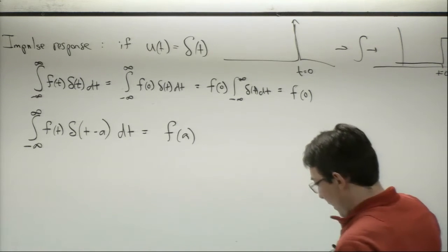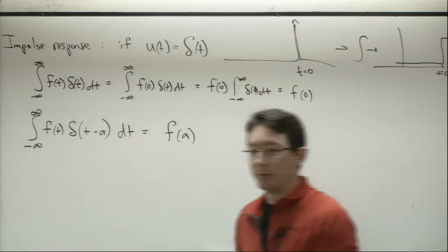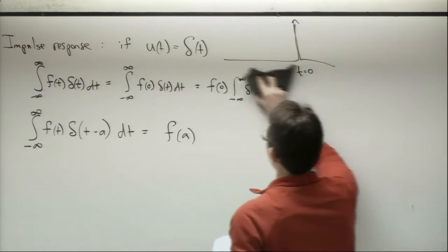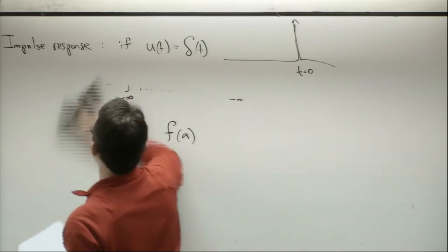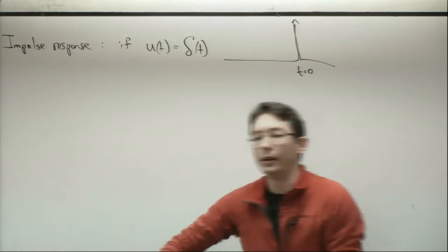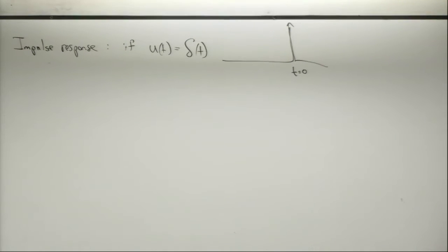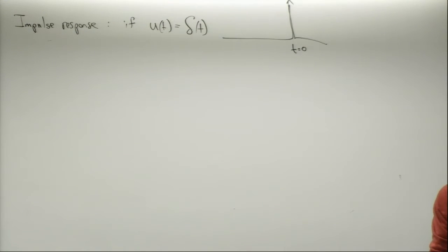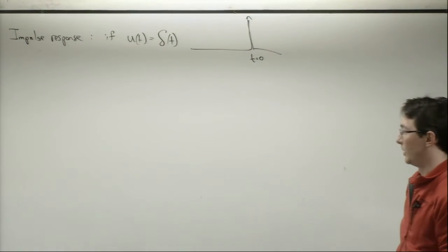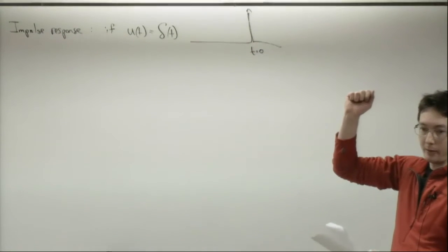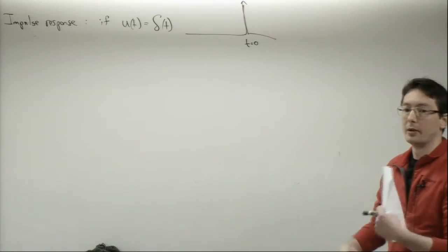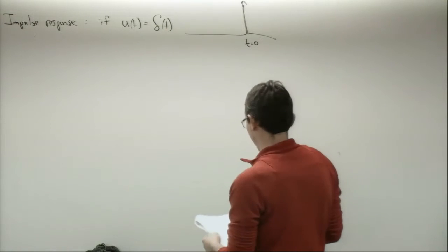So we're going to be using this delta function impulse response, and we're going to start thinking about how our system responds to it. The really cool thing about a delta function is that even though it has infinite magnitude, it occurs in an infinitesimal window, and so it only adds a finite amount of energy to my system. It doesn't make my system blow up. It's just like taking my spring mass damper and hitting it with a hammer. It might happen very quickly, with a very high magnitude force, but it only adds a finite amount of energy to the system.